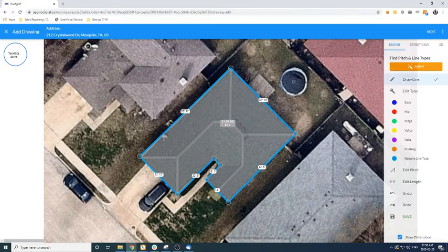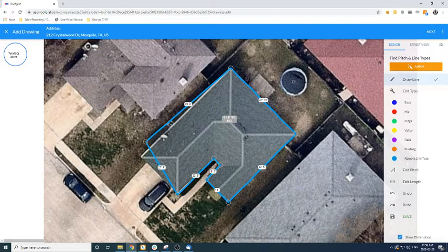And you'll notice as well, guys, there's a function here that tries to find perfect right angles. We assume that all of these buildings are built at perfect right angles. If that's preventing you from getting your point exactly where it should be, if you are on a desktop, you can hold the Shift key, and that will disable the function that attempts to click into perfect right angles. That way you can drop this point exactly where you would like.